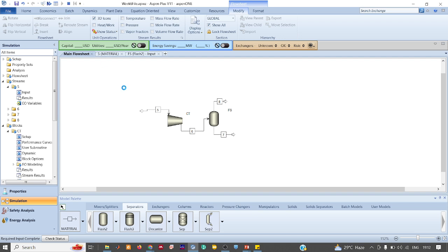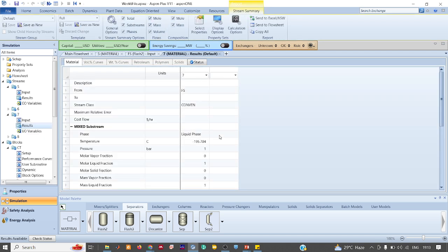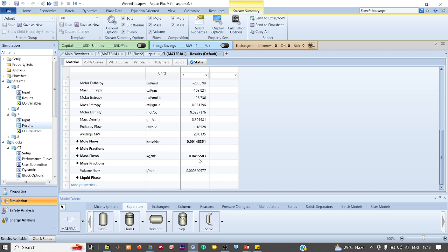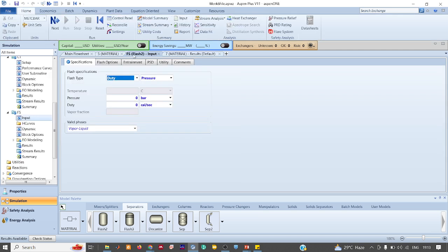It's the zero bar pressure drop. If you are assuming one bar, that means you are giving the pressure or the outlet pressure, if I remember correctly. Let me just see the value. Output of the turbine is 1 bar. See, it says absolute value, outlet pressure value is greater than 0. Pressure drop if value is less than or equal to 0. So yeah, you can write it as 1 bar also. It means the same.